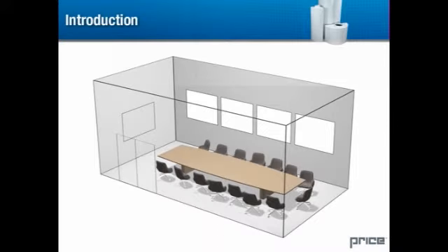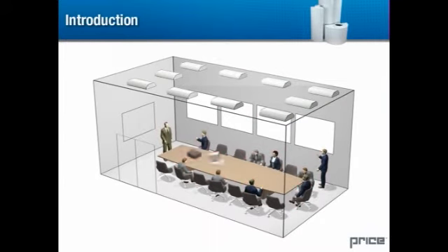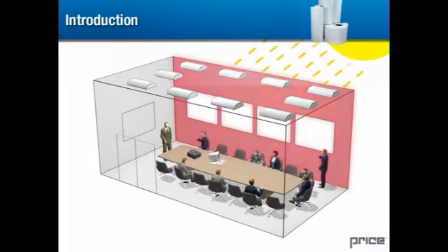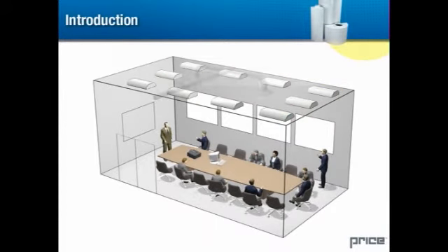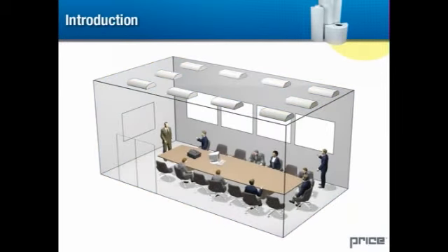For all displacement ventilation systems, the load calculations are quite different than they are for traditional mixing systems. The cooling load of a room or a space is determined by the heat sources present, such as lights, occupants, equipment, and solar gain. Because a mixing system cools the entire volume of the space, we must account for all of the heat sources in our calculation.